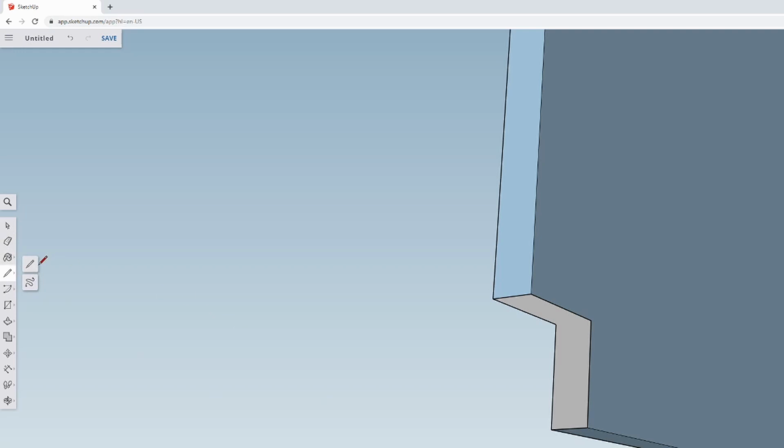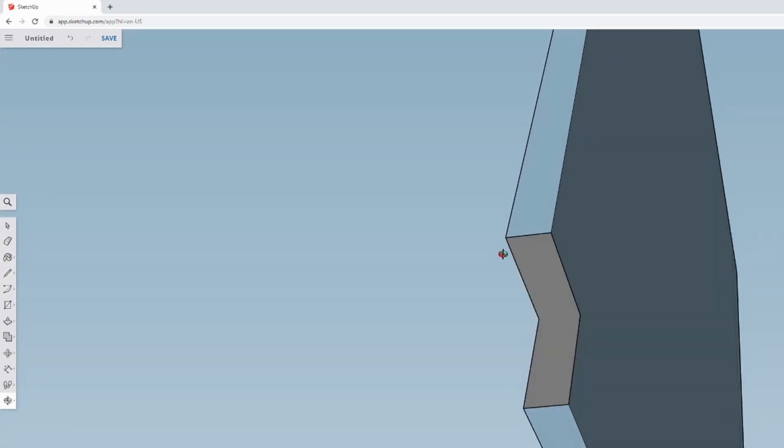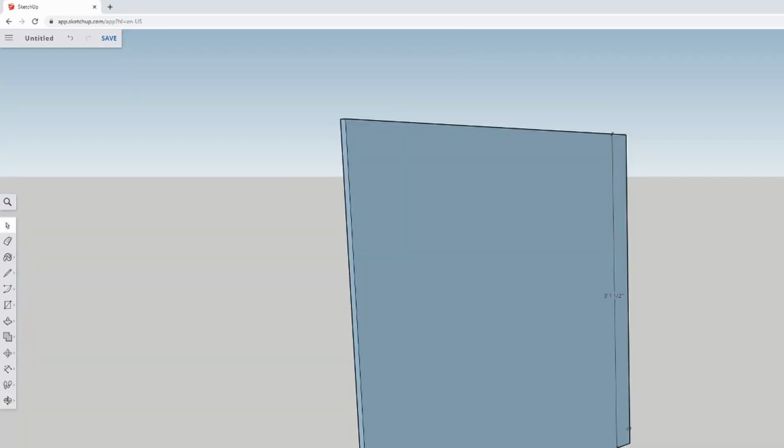Now, because this is still 3D, this inner piece is hollow, right? So I want this to look solid, so I'm just going to create another endpoint, and that will automatically fill in these two planes, so this way it represents the pure 3 dimensions. As part of that, I deleted my dimensional line that went along the long axis, so let me just redraw that.